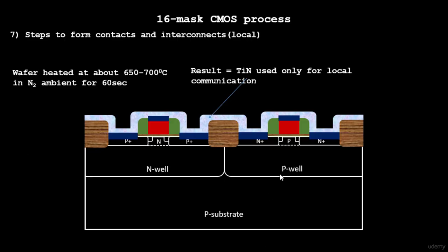Hello everyone, let's continue our discussion with the source and drain formation. The next step is to add a thin layer of screen oxide over here. I just added a small thin layer of screen oxide, and the reason for that is to avoid the effect of channeling.